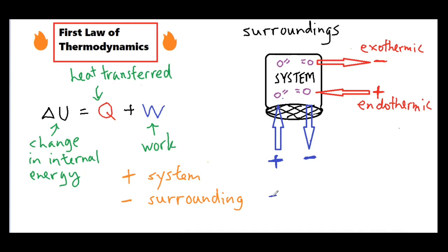So that would actually flip these signs, and it would be negative over here and positive over here, because if you're taking the view of the surroundings, then the system is pumping out energy to you, which would be considered positive, or the surroundings are pumping energy into the system. Therefore, you would be losing energy by transferring it to the system. Okay, as I said before, in my experience, this is the most predominant convention. So we're going to go with that one and the plus sign between the Q and the W.